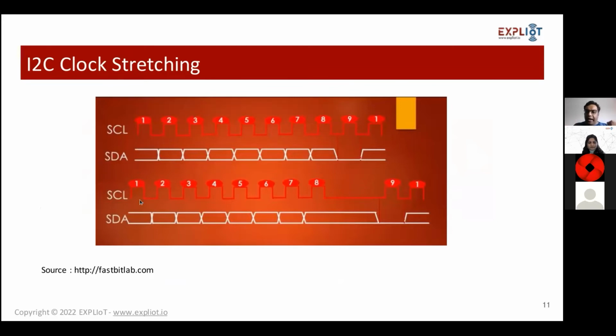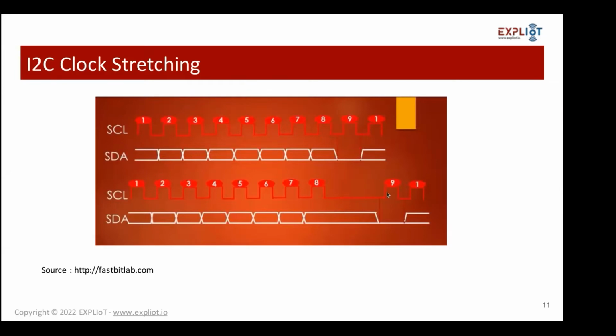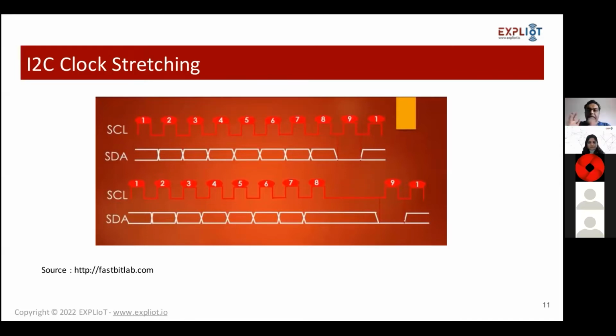The clock is progressing ahead and ahead, and for the next bits of data, when we have acknowledgement and the data being sent again and again from the master, the slave will not be able to handle that speed of the communication. In that scenario it will send a negative acknowledgement because it is not able to handle that clock itself. So that gives a false NACK, I'll say. So it's a failure of the communication.